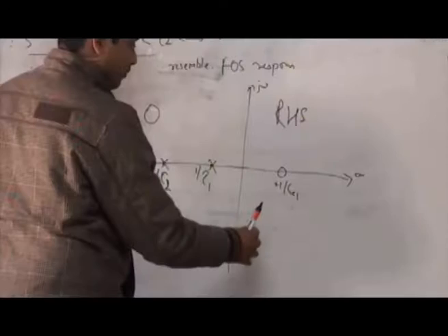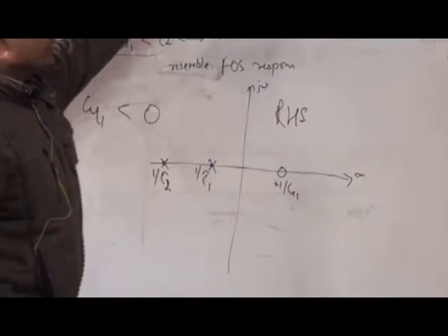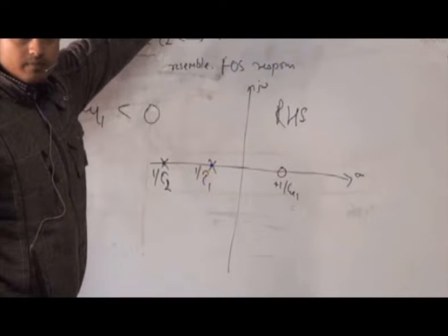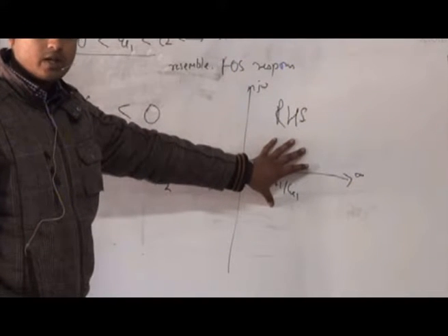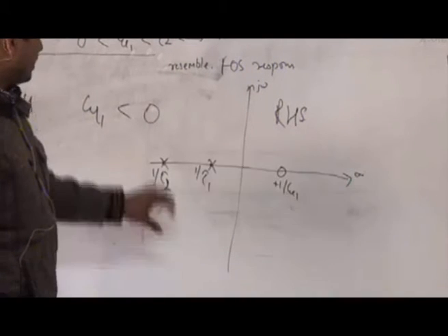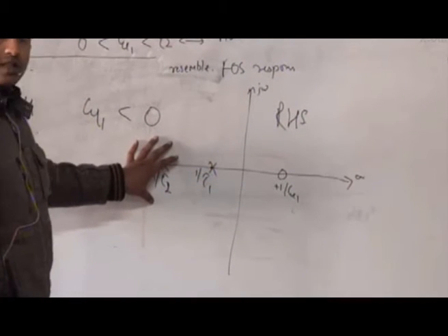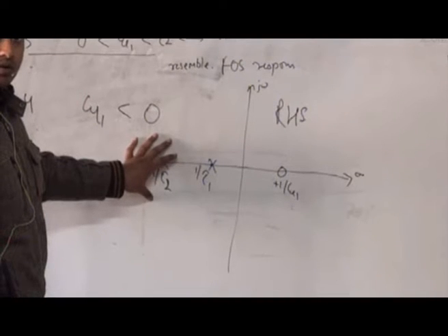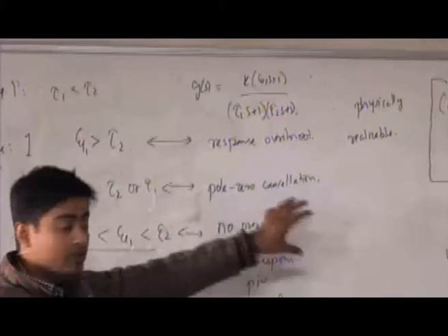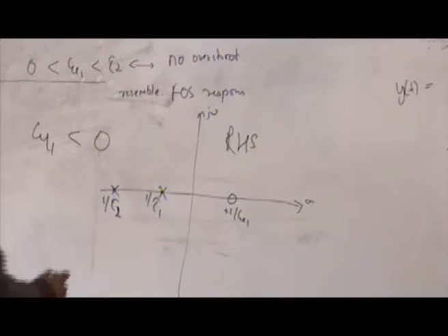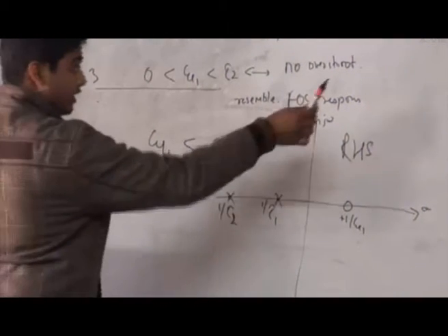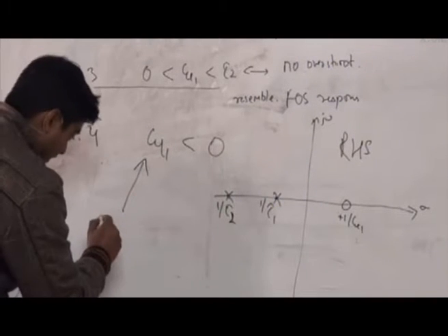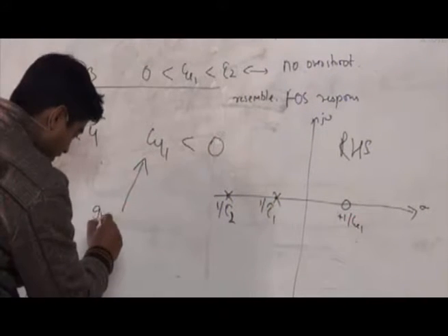Okay, but the stability is generally governed by just the poles of the system. Then how does the zero play a role in determining the stability? Now this question must be coming into your mind. Since the poles just govern the stability, what will happen if I move my zero to the right hand side? The system will still be stable. No, so this scenario is called... if you put this condition into that y(t) signal, you will get a response which is called an inverse response.